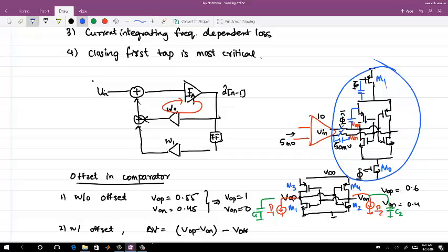So you are having a capacitor everywhere. This is not what you are putting deliberately. This is something which is coming on its own. Whenever a switch opens and closes, you have a charge injection going in different directions, in the direction where you find a lower impedance. So what this does is it actually gives a kickback to the previous node.